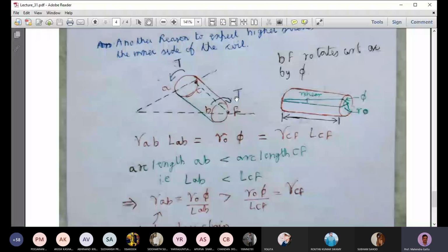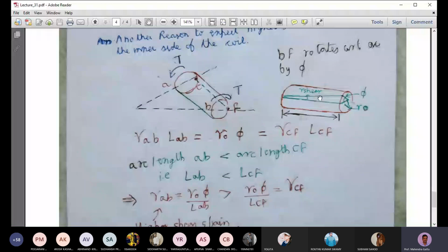And L is this AB. So one thing before doing that, we'll just look at this figure in a different way. This is the length, and this is the horizontal line, which is the deformed shape, and due to the twisting moment, it will deform. This point will move along the arc and reach this point, and this angle subtended to the center is phi.